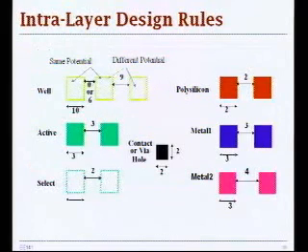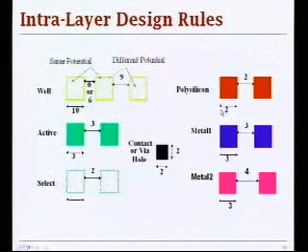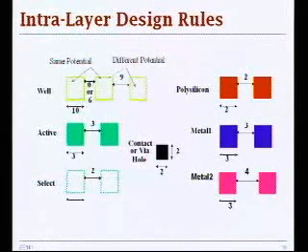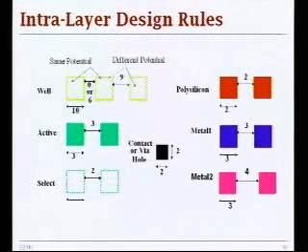So interlayer design rules specify widths and spacings of objects on the same layer. And for example, you will find that the minimum width of your polysilicon will be 0.24 micron. That's represented here as 2. That's basically your lambda, 2 lambda. That is, for this process, 0.12 is lambda. So that defines your minimum channel length. You will have 0.24 is your minimum channel length.